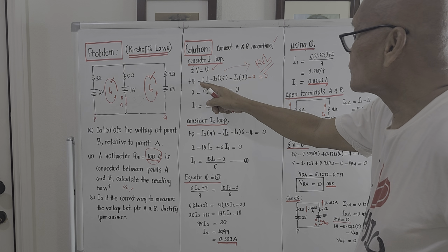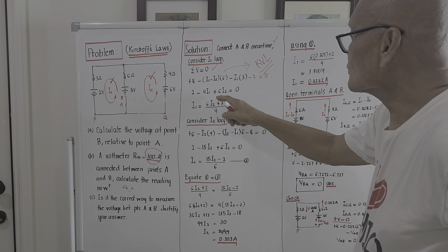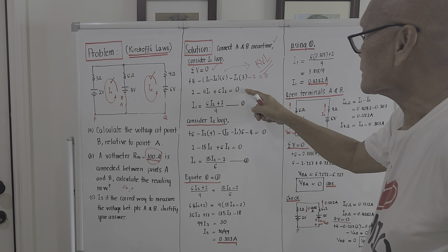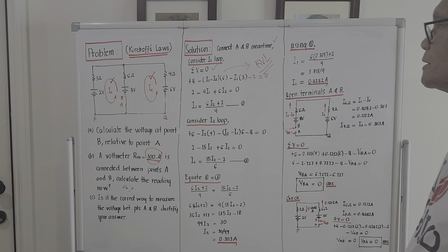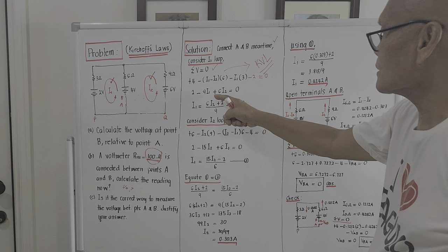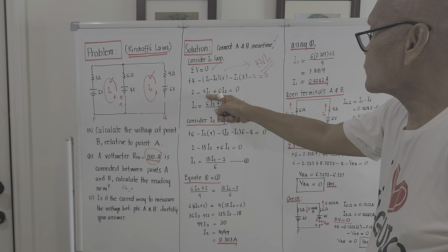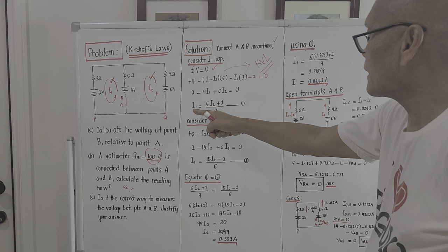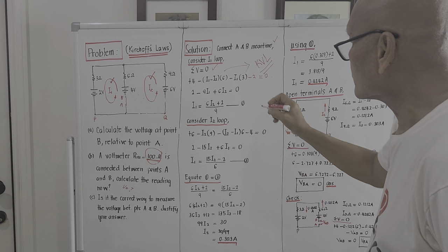And I sub 2 will now be plus, because this is minus minus. So plus I sub 2 multiplied by 6, and this should be equal to 0. Trying to compute for I sub 1, this is linear algebra. We transpose this one to the right, then we divide both sides by 9. So I1 will be (6 I sub 2 plus 2) over 9, and we call this equation number 1.